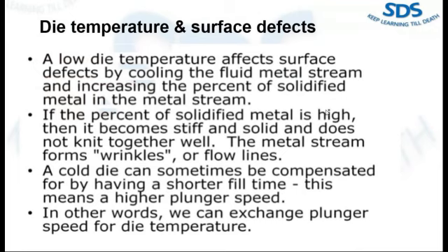So how logically is die temperature a factor? Yeah, we can imagine die temperature is a factor for generating the surface defect. But how can we logically understand it, how can we say it with the help of some formula? So this is the way. This is the filling time formula. There's a variable or parameter, percentage of solid. So as we decrease the die temperature, we increase the percentage of solid, which also increases the cavity fill time.